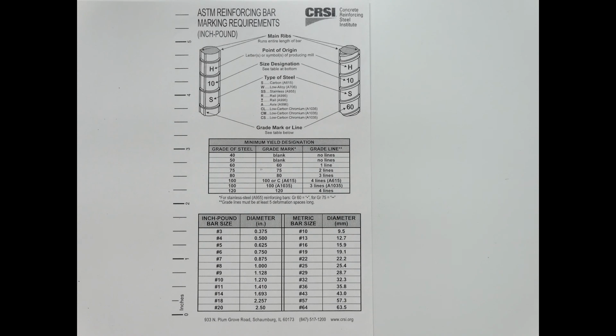Was there any thought process other than right at the end where we didn't like the spacing? No. It's formulaic, right? If you give me the shear, these equations will tell me what my spacing has to be. And that's really what computers are for. So you can expect to do a little exercise by hand, calculate some shear calculations just like this, and then we'll move on to the computer program.